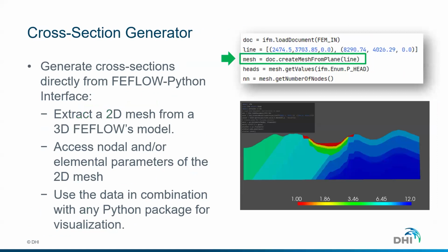On top of that, many people started asking, and also internally at the HI we needed the possibility to create cross sections directly with FEFLOW. How does FEFLOW operate in the graphical interface? Quite simple. You create polylines, and for these polylines you can ask the software to build a cross section. When we do this in the graphical interface, we create a pseudo mesh in 2D. We do the same now in Python.